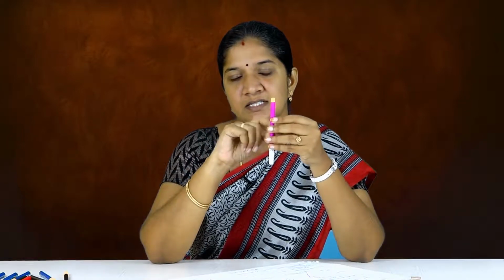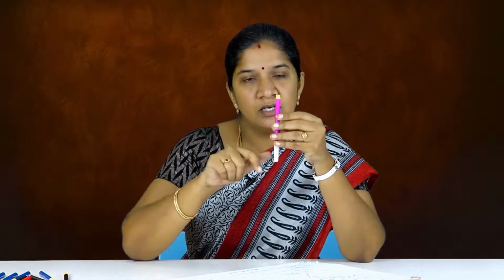Here this reinforcement will act as hanger bars. Hanger bars, in the sense that I want to provide shear stirrups around my main reinforcement layer. So a box-type layer will be provided as reinforcement, that is called shear reinforcement. To hold the shear reinforcement, I need two bars to be laid down in the top region also. Those bars we call hanger bars in the case of a singly reinforced section. Okay, let me come to the doubly reinforced section.